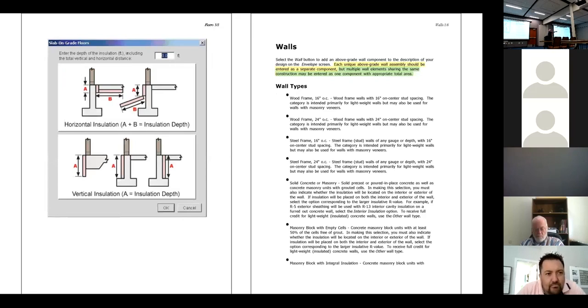And someone mentioned, that's what I was referring to, is more form slab on grade. Conditioning foundation. Yeah, these are energy pigs if we don't do them right, and they're very often not done right. But the table and the study was looking at the potential savings in Utah. And since we don't have that much slab on grade, it didn't make as big a difference as some of the other things, simply because we don't put it on everything.